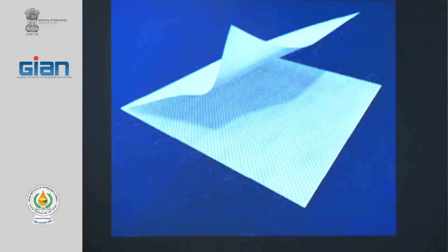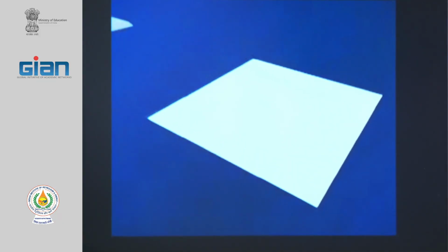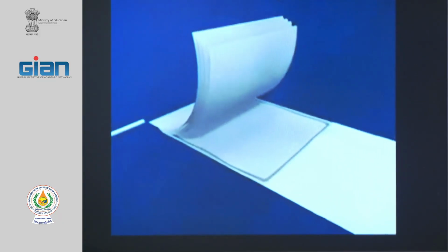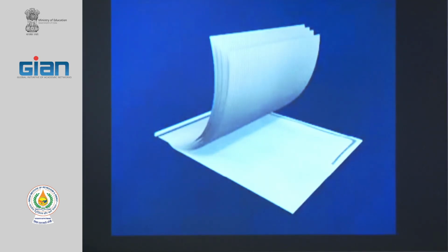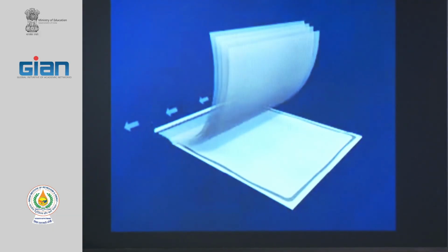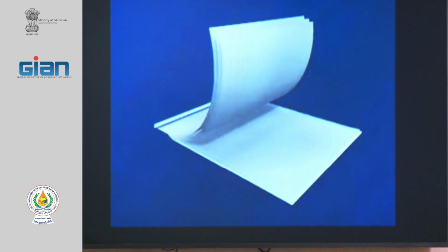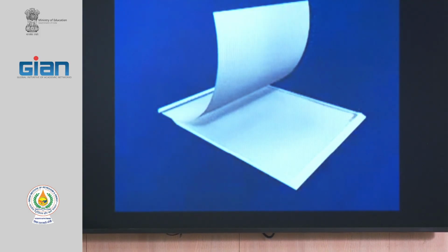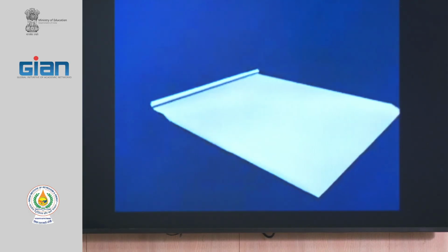The membrane flat sheet is then combined with a sheet of feed channel spacer. This provides turbulence and creates space between the membrane sheets to allow uniform flow of the water to the entire membrane. All of the permeate goes to the central tube. The membranes are then combined with a sheet of permeate spacer, which provides open flow channels. Usually for 8-inch modules, we have 24 envelopes. Sleeves are glued along each of the 3 exposed sides.